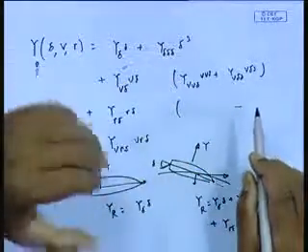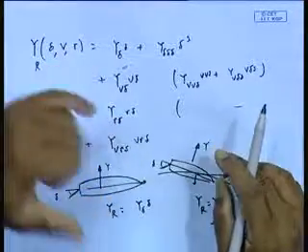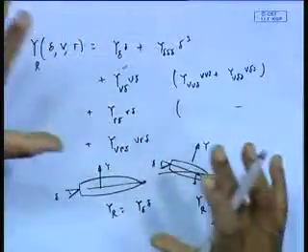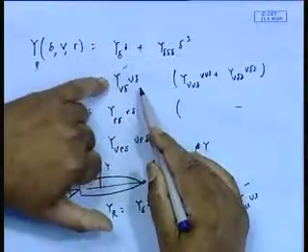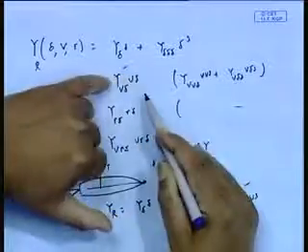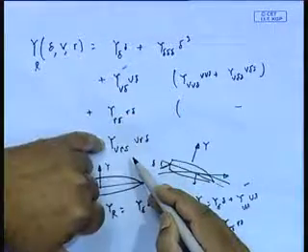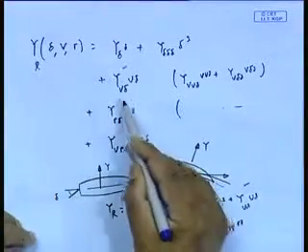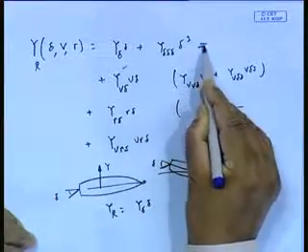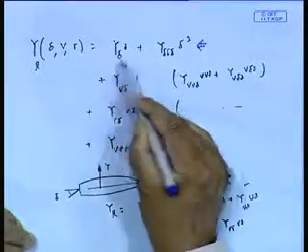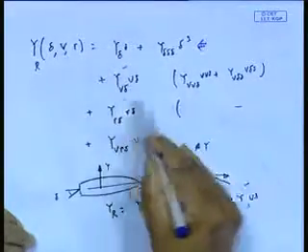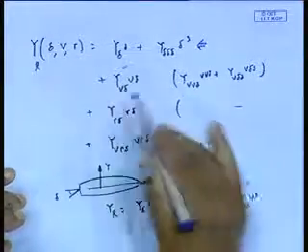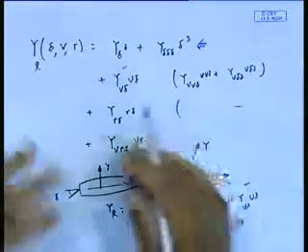There are two dominant schools: one is the European HSVA model, one is the so-called American model. Some people take only this and this, some people take this instead of this. But most people will take a coupled term. These are the non-coupled terms because they just tell me y varying with delta. These, like v delta, are what are called coupled derivatives. This is a question of modeling.